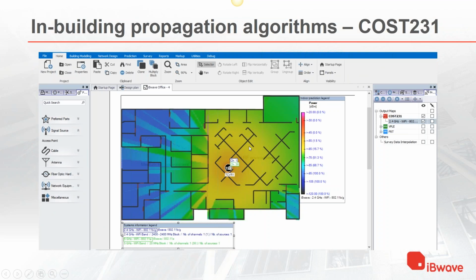You see this is an office space. What you see here is a break room in the top corner, and then there are individual offices around, and in the middle is the cubicle area. So the antenna is pretty much in the middle. And then what you are seeing is shadows that don't look very natural. Okay, you have a very sharp drop when you move just a little bit. And this is not really what you should expect in real life when you go out and observe how the signal changes when you are not in line of sight. The signal should not drop all of a sudden 10 dB and stay there.